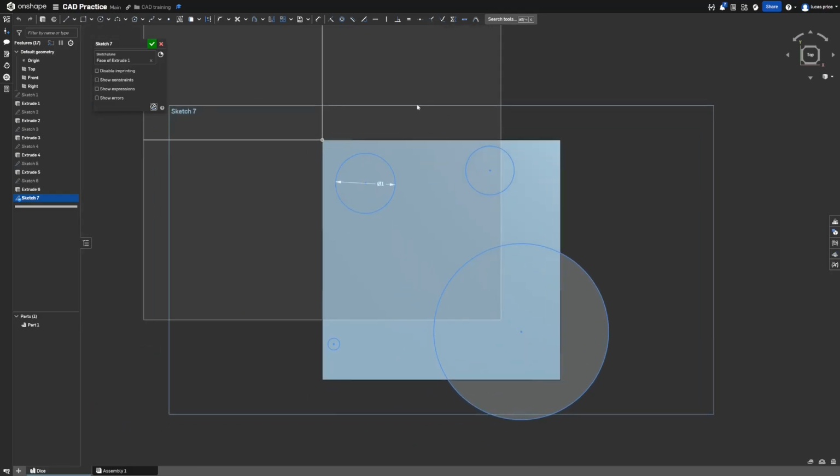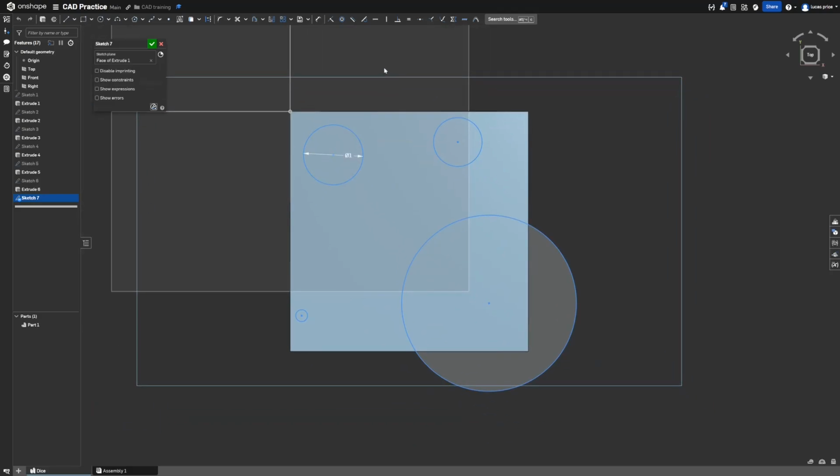As well as I'm going to show you guys how to make these things easier without having to put so many dimensions in and cluttering up the screen. So first we have just one circle dimensioned to 1 inch, the rest are just random. We're going to use this equals tool up here at the top, and we're going to click this circle and make it equal to this circle. It will go off this circle because this one is dimensioned. If they're both dimensioned differently, it won't work.